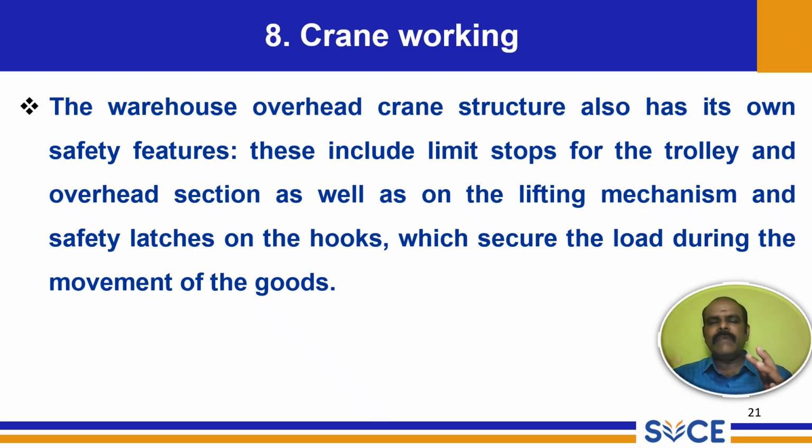Again, on the safety feature, let us compare to the lift car of an electric hoist. That is nothing but a lift that we have in a building. Clear? In a building, a lift might have a maximum number of passengers, say 5 passengers, or weight, whichever comes first. The moment extra load comes, immediately we have a warning system. That warning system will warn us of overweight or whatever may be the case, and immediately one deboards, then obviously the system works. Likewise, here limit switches are there, then strain gauges are provided to identify the load, etc. All sorts of safety features are considered.